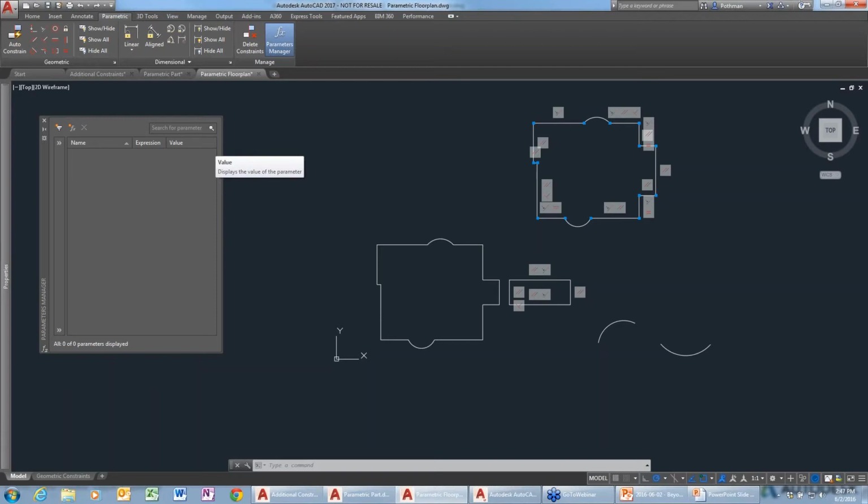There are lots of other things you can do with dynamic blocks, like setting increment values and using tables and all kinds of stuff. But I don't see why you wouldn't be able to use a constraint like a concentric constraint on something. So as I change the diameter of a circle, another circle will change accordingly. Pretty sure that would work.